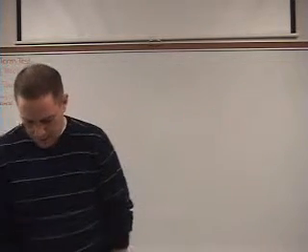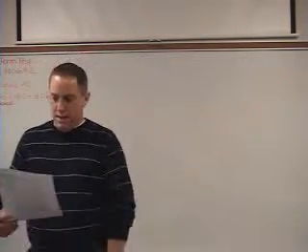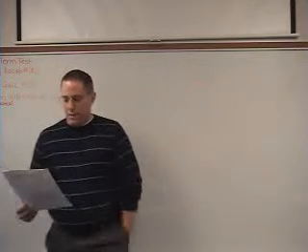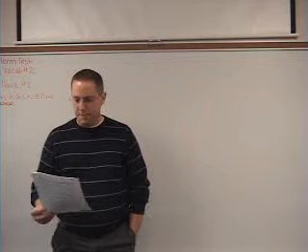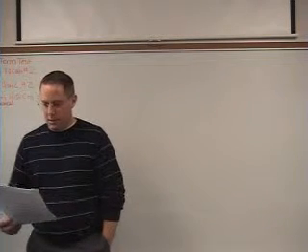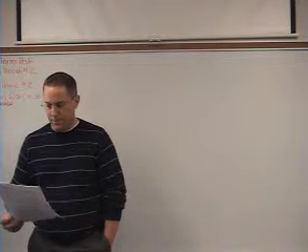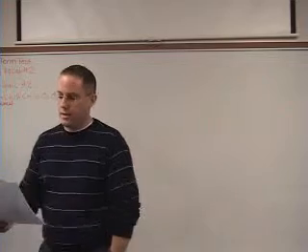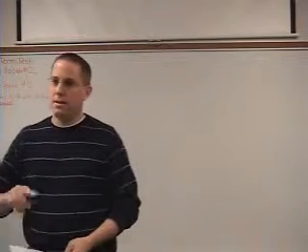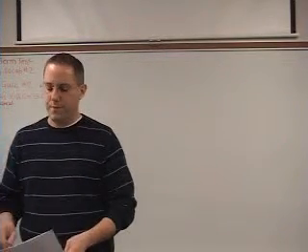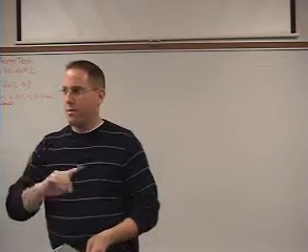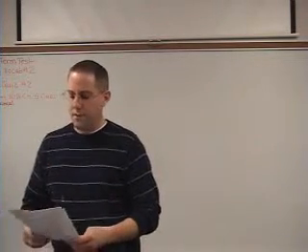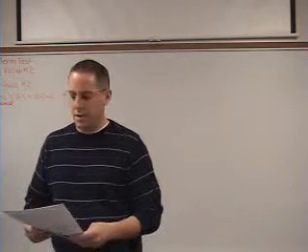And here on the notes in the middle, it tells you what you could see that would tell you that something's wrong. It says when an exposure is made, the MA meter should only move to the MA that was selected. Okay, so if you selected, let's say 100 MA, the needle is supposed to move up to 100. All right. If the needle bounces back and forth instead of stopping, then you know there's something wrong with the X-ray machine.